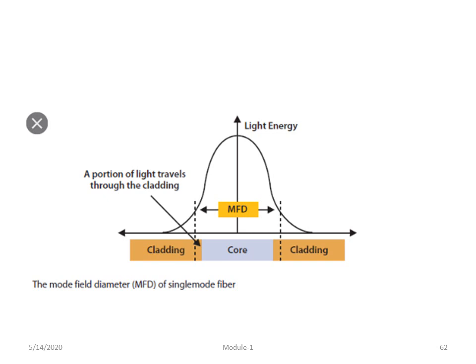Single mode fiber allows only one mode, but how do we design the fiber as a single mode? The normalized frequency must be less than 2.405, the wavelength must be greater than the cutoff wavelength, and the mode field diameter should be considered for the single mode fiber. These concepts we need to explain for the single mode fiber. What are the different design approaches?